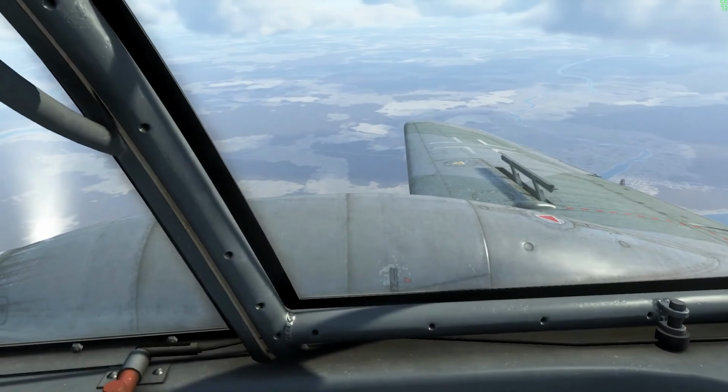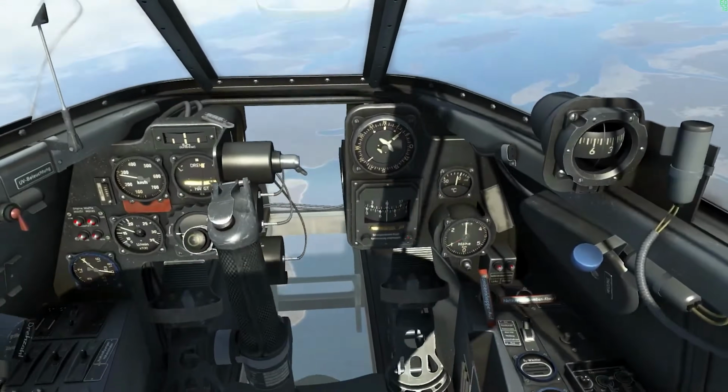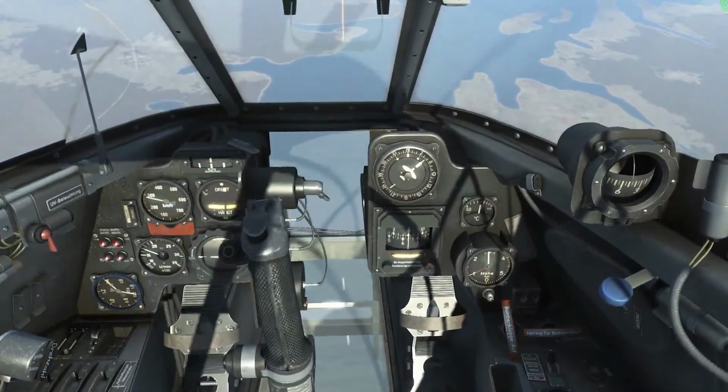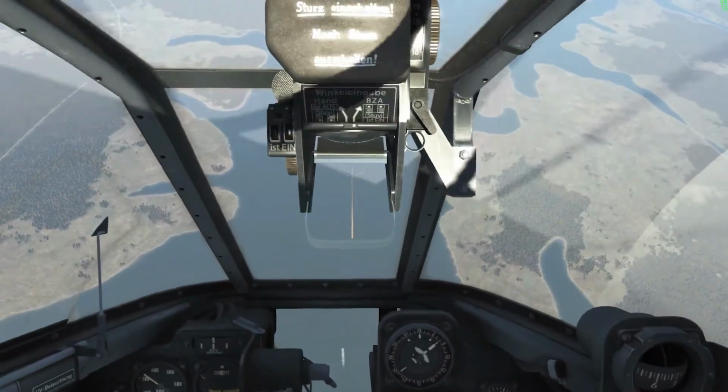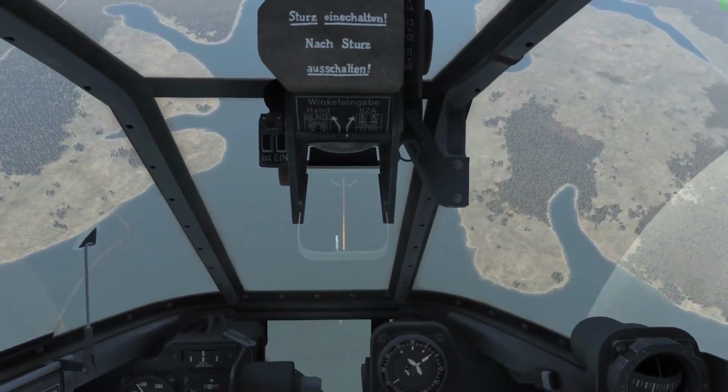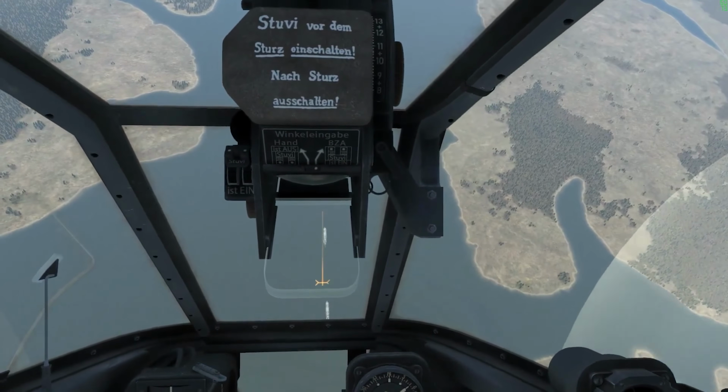Follow the target until it appears about halfway down the nose window. Close the radiators and set the propeller pitch to 100%. The dive angle should be about 50%. Note the approach of the bow tie or cravata bomb sight below the main sight. Hold the target on the line until you hear the drop altitude warning buzzer.